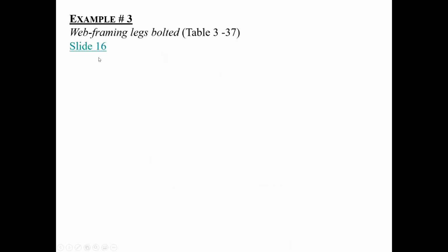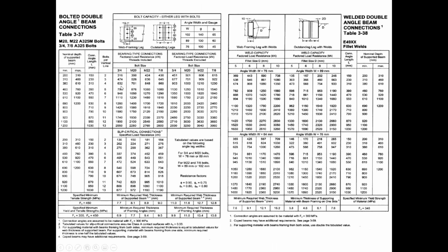Now, here, I said 3/4 inch bolts, okay, and therefore, now my beam happens to fall here. I know that this VR value is ample, but I'm not even going to use that. I'm going to go based on the geometry, for a much higher VR value, okay? And because my beam is greater than this, I'm going to put it in between this, and I don't care if I have 474, I only need 64. As far as the geometry goes, good practice means I should be using this as my connection, and that's what I will be doing.